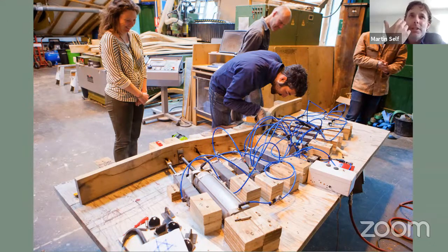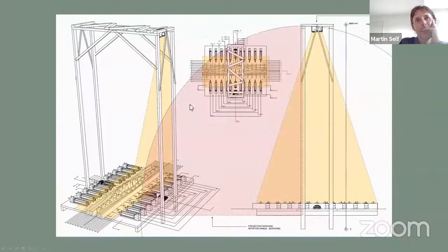What's clever about it is that the grain continuity of a straight plank gets preserved in the curved shape. If you compare it to taking a block of wood and carving a shape out of it, you'd break the grain and get a short grain, where the grain wouldn't align with the piece of wood. But through steam bending, you do have that benefit.